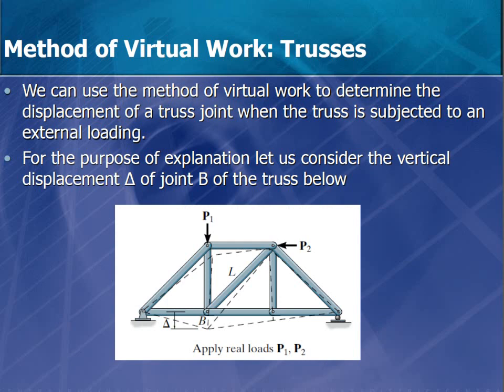So let's explain this in a truss to be much clearer about what we're talking about. Now, in a truss we don't have moment, so the only form of deformation, or the part of internal energy that we have here, will be due to the normal forces. Now when I say normal force, remember the whole structure works together to resist the load.